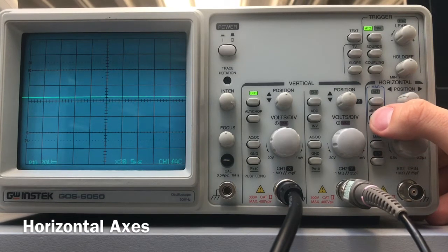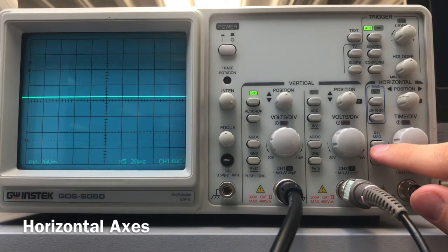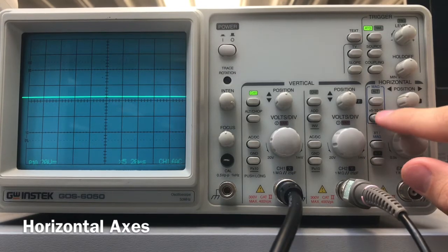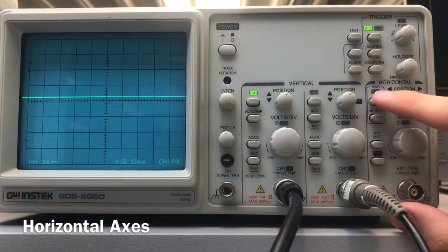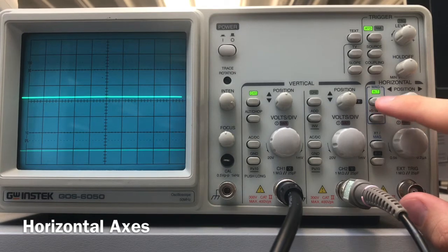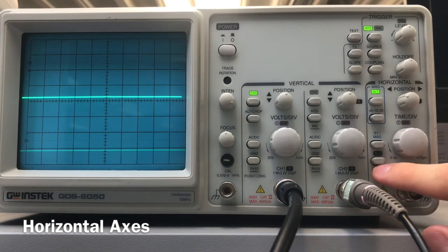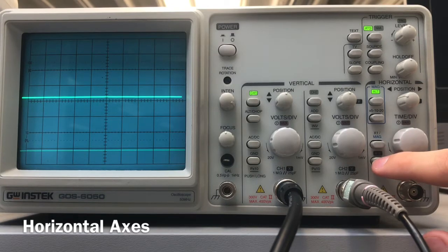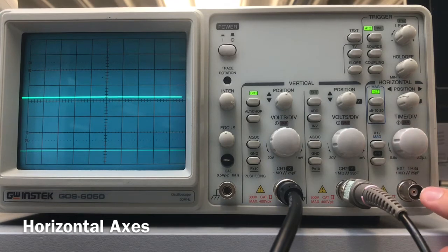Just switch it from 5 to 10 by pressing here the magnification on, and then this. And then to compare your signal to the magnified one, you can press the out when it's on. Finally, you've got the XY button, which basically lets you vary the vertical and horizontal movement of the beam by varying the X and Y. You can also attach an external signal to trigger the source.